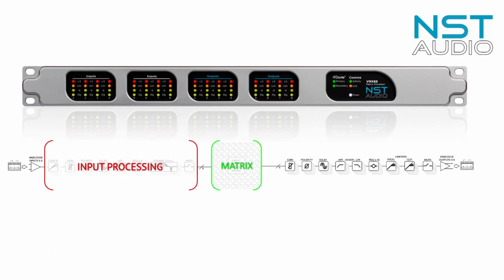Output channel processing makeup is slightly different. Each output channel has available output gain, polarity, phase reverse switch, with an additional 1.3 seconds of delay. Crossover filters, that is, high and low pass filters with a selection of types and roll-offs, this time up to 48 dB per octave. A full 16 bands of parametric EQ, with all the features of the input EQ. 2-stage look-ahead limiters. So, RMS limiting for power output control to reduce voice coil overheating, plus, peak limiting for speaker excursion control to mitigate against mechanical damage. And finally, an output mute.